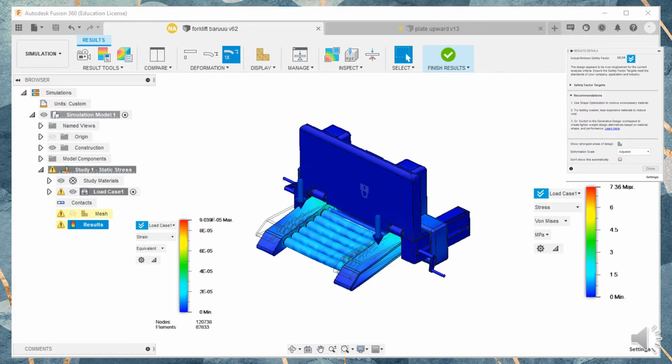Before that, we are going to choose the material for the compartment. After we choose that, and we undergo the process of analysis, we are going to find the safety factor. The safety factor shows if we are choosing the right material for the compartment. We can also see the amount of stress put on the surface that we choose. After we put force on it, we can also calculate strain and many more. Next, I'm going to talk about optimization on the next slide.